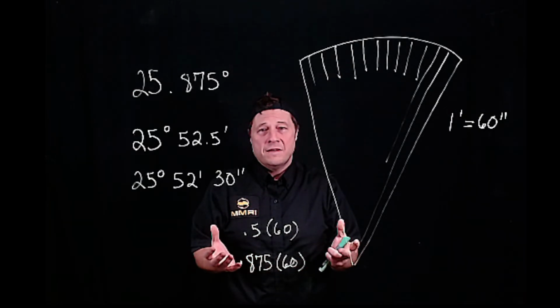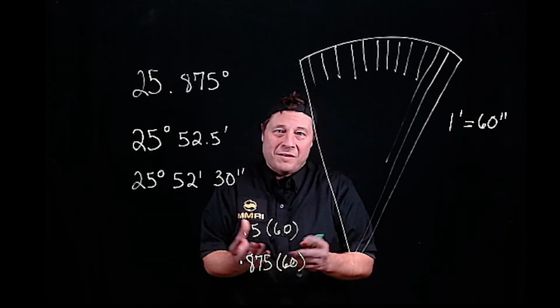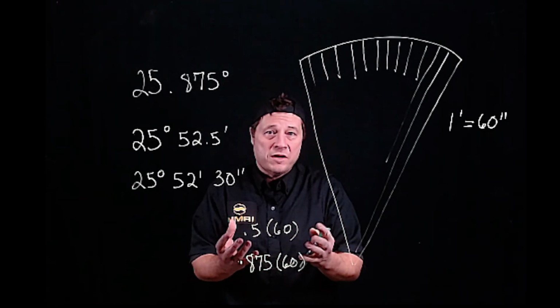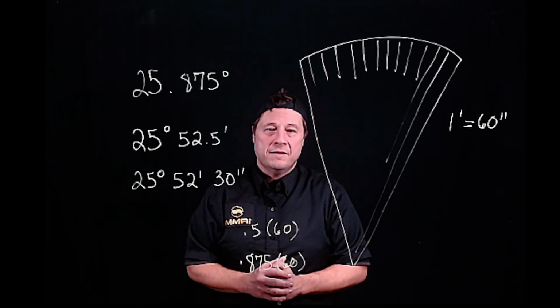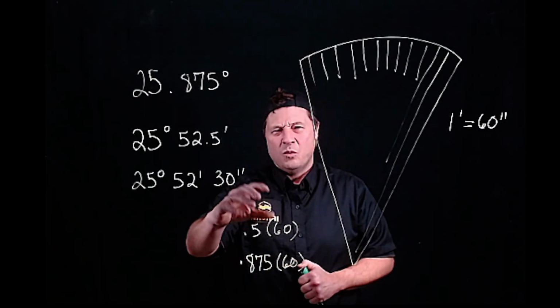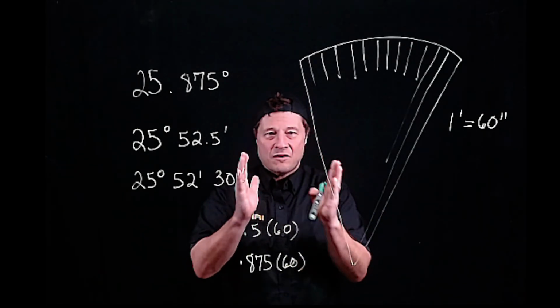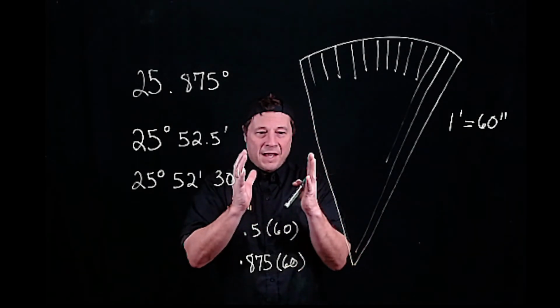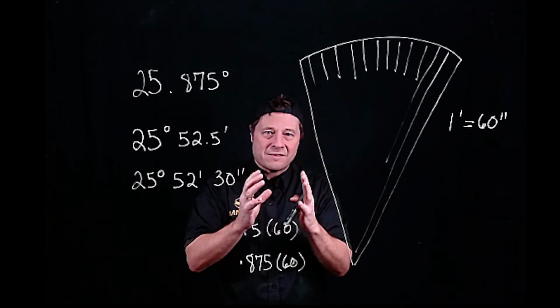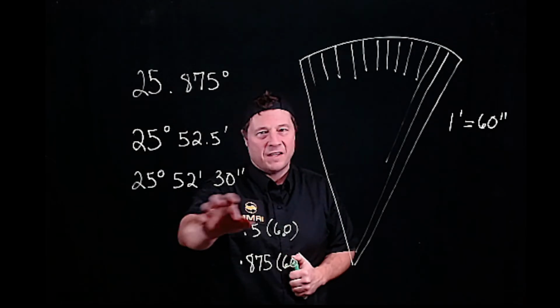Which is fine for a lot of applications. And as machinists, we're like, well, if we're within plus or minus half a degree, we're good because we can do that. But now when you start thinking about accuracy to 1 minute or seconds, you got to start thinking about how precise that measurement is, the requirement, and how do you measure something so precise.